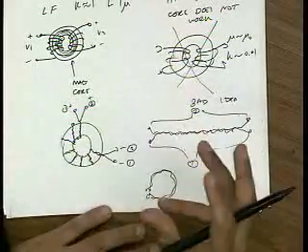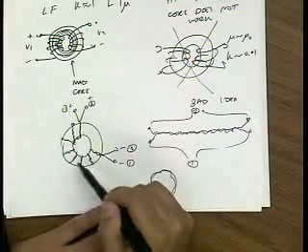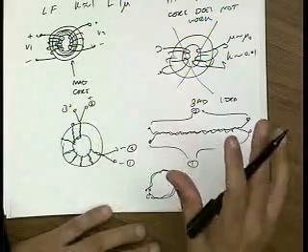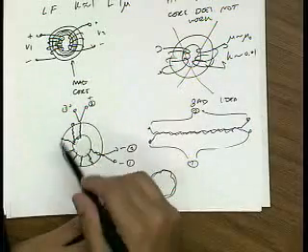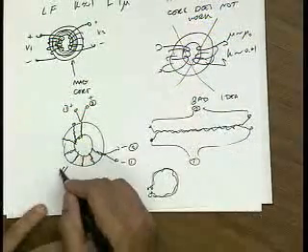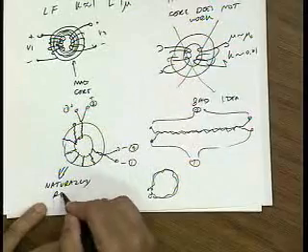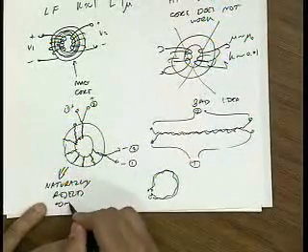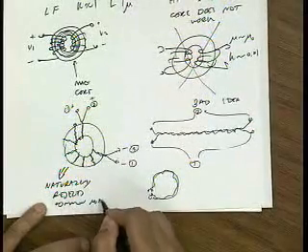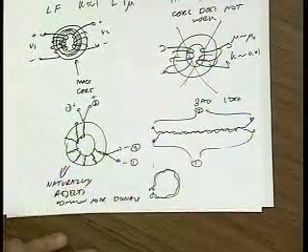So they make our mu imaginary. For a differential signal, because there's very little magnetization, there's very little loss. But for a common mode signal, there's lots of magnetization and therefore lots of loss. So this structure naturally rejects common mode signals. And later on, we'll see why we want to reject common mode signals.